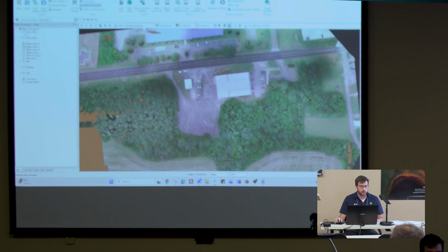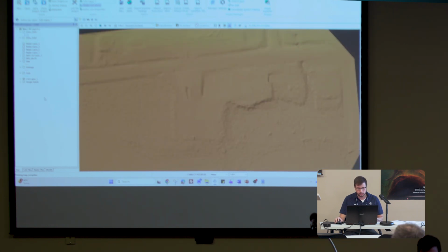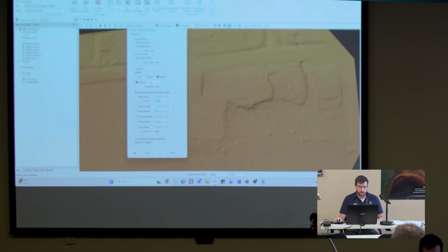So I'm going to turn off my raster layer. Let's just look at just the LAS data. Click on the point task at the top, and in your PCT group that I gave you, click on the ground thinning option and click on the active PCT settings. And basically I'm choosing a cell size of 1 foot, and I'm basically making a 10 points per square foot thinning here.